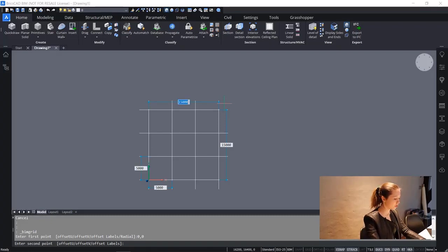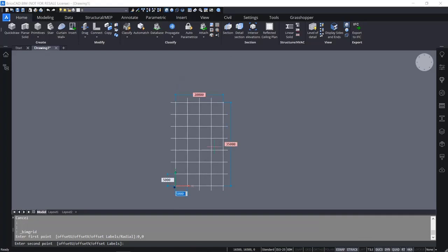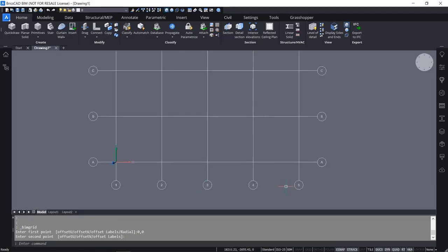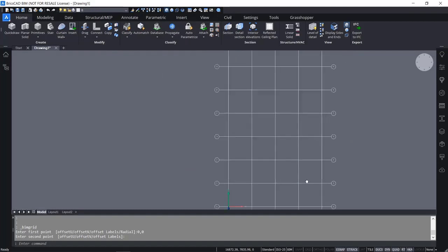And then we go to 20,000, the width, and the length on 35,000. So if I press tab, I can switch to the next dynamic dimension, and you see the preview of the already put in values. If I now press enter, it will accept those defaults. And then you will see a grid is created, which is automatically numbered from 1 to 5 and from A till H.